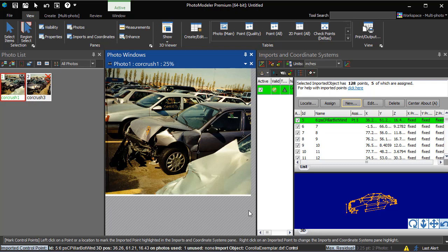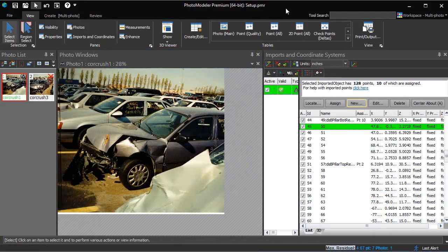If the points marked did not have sufficient spread across the photo, you may get an orientation failed message. In this case, you would confirm the points marked so far are correct, and possibly mark more points to strengthen the project before the orientation succeeds. Here, on photo 1, we have marked additional control points on undamaged parts of the vehicle to strengthen the project's solution. We have reviewed our marked locations and checked the residuals to make sure the project is solving well.